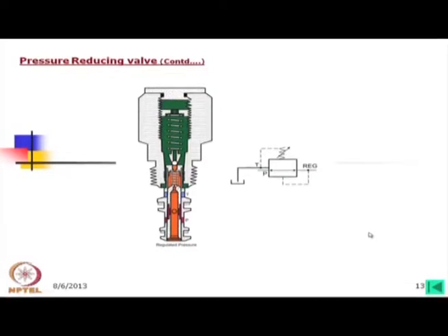Now, this is another pressure reducing valve which is called cartridge drive. As you see here, you can study this part. This is the pressure line, okay, oil is coming over here and this is the main spool which moves depending on the regulation here, and then flow goes to the tank through this part.